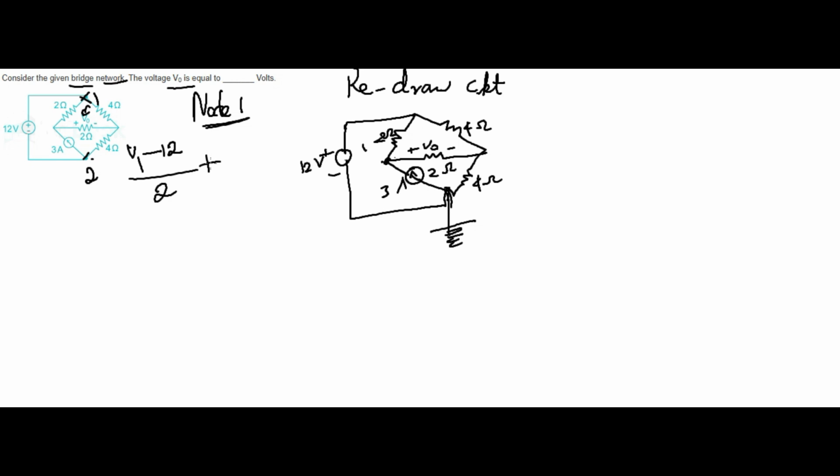Then you have to add. Okay, so here another voltage is here. It's right, this voltage. So you can make it as V1, V2. Okay, just forgot to tell you. So here V1 minus V2. This voltage you have to subtract. Previously this voltage you made a minus, right? Now this voltage you have to subtract divided by the connected resistors. Connected resistors means what? In between V1 and V2, 2 ohm is there, right?